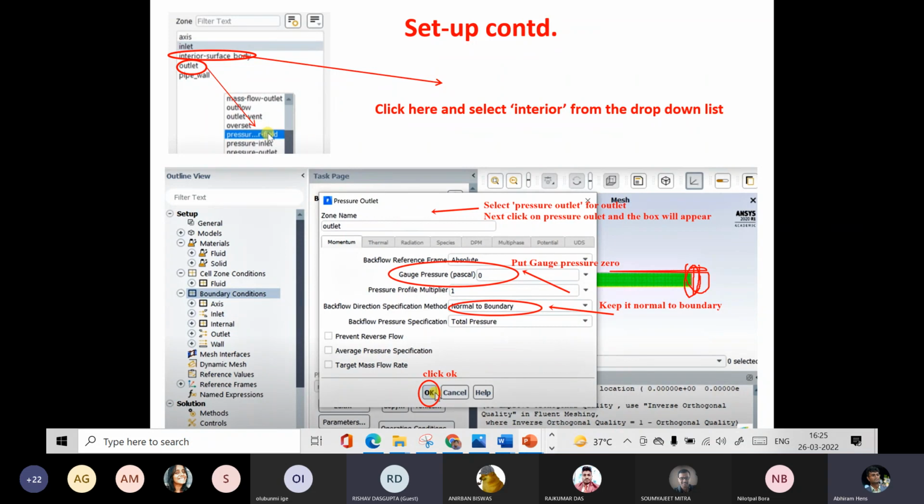Okay. So actually outlet boundary condition is not precisely mentioned in the problem. Okay, so we are going to give del p del x equal to 0. If you realistically think, when fluid is flowing in a pipe and going out of it into the normal atmosphere, it's a free flowing condition. Okay, no more thing is there, no pressure is there. So that's why we are defining gauge pressure as 0. Okay, so that means there is no additional pressure, it will freely move out from the tube. Okay, so that's why we are mentioning it 0.